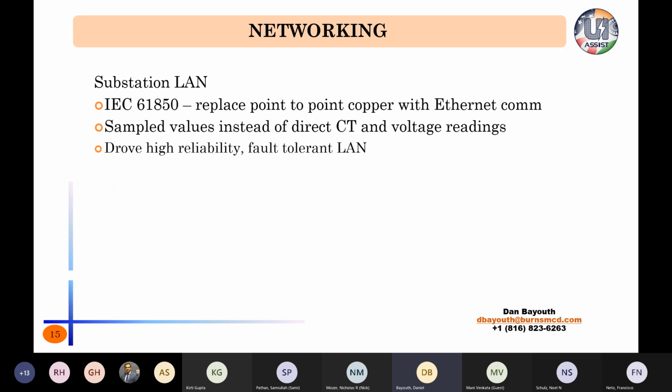So we get a current reading in the yard that gets translated into a data value that's pulled into the substation. So I'm moving all that high voltage, high current stuff, and where that used to come into the station to read it, pushing that back out to the station to isolate my electronics more than they used to be.